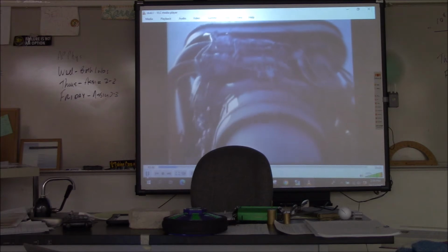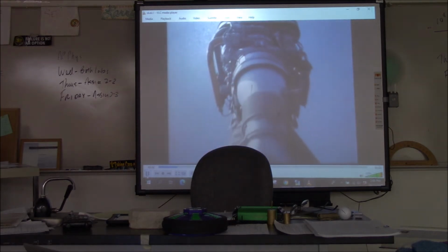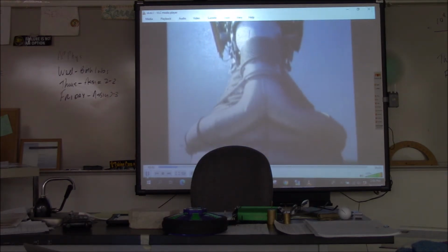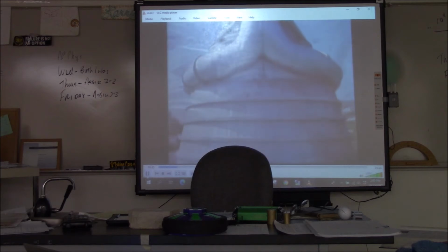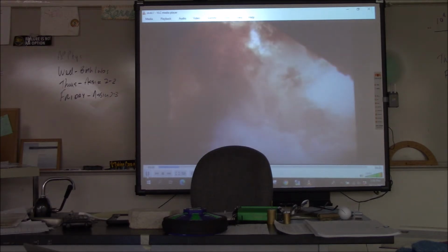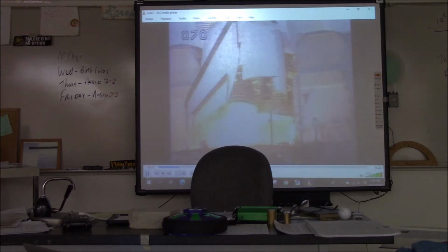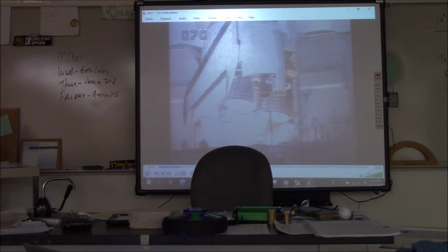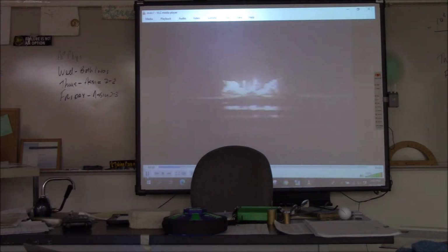In the combustion chamber of the rocket engine, the propellants are consumed in a combustion reaction. The thermal energy generated from the combustion heats the newly formed gases to extremely high temperatures. These gases, possessing a large quantity of kinetic energy, subsequently go through an expansion of the rocket nozzle and are ejected at extremely high velocities. With the fuel being composed of liquid hydrogen and liquid oxygen, the hot gas which is expelled from the engine is primarily water vapor.